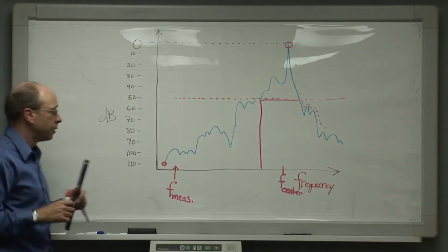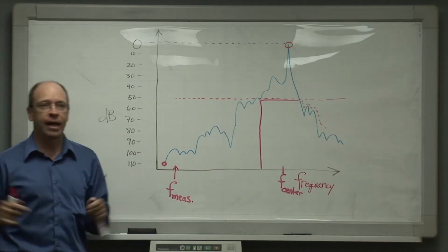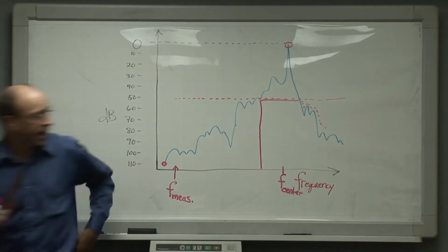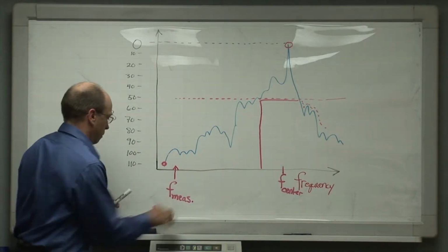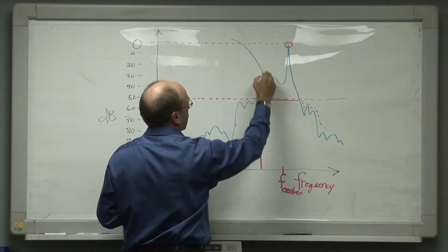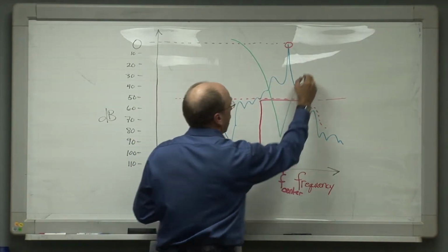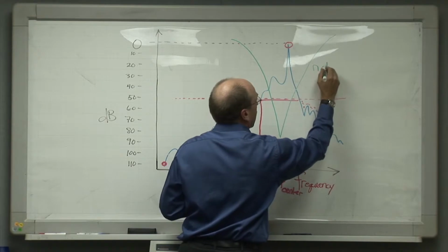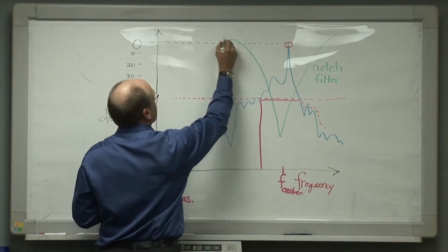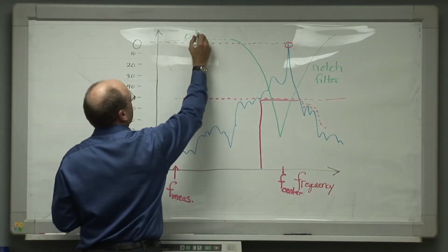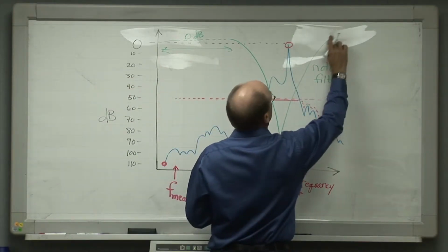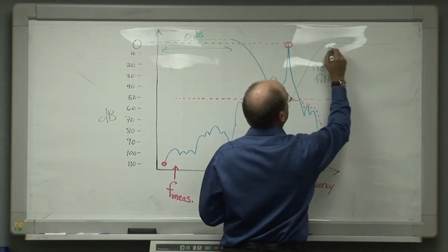Now, here's one way that you can do this measurement, as I've diagrammed here. If you're trapped on a desert island and you've got no other options available, you don't know what to do, you can obtain, by hook or by crook, a notch filter, which might have a passband that looks like this, such that basically the notch has 0 dB of attenuation across this frequency range here and across this frequency range here.